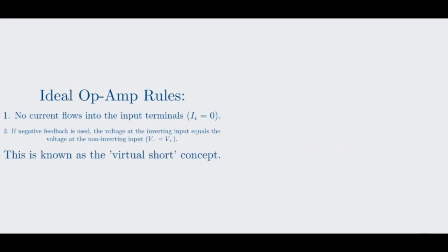Now, of course, a real op-amp isn't ideal. It has limits on its output current, bandwidth, and slew rate. But for most applications, the ideal model is an excellent starting point. So, how is this magical device built on the inside? An op-amp is an integrated circuit containing anywhere from 6 to 20 or more transistors, depending on its complexity. Its structure is usually divided into three main stages. Let's look at a conceptual block diagram.